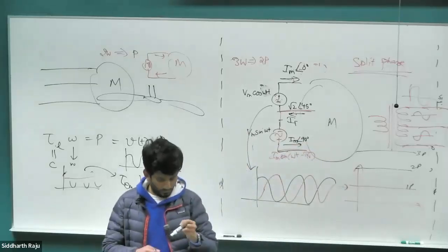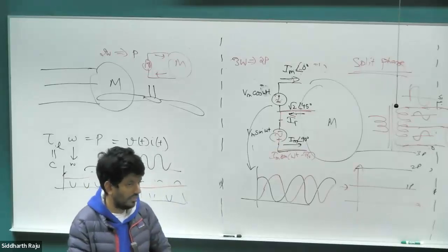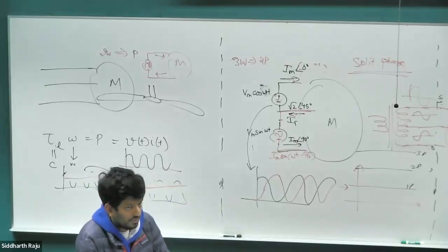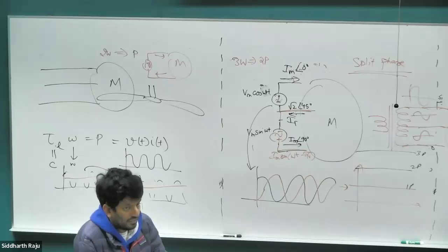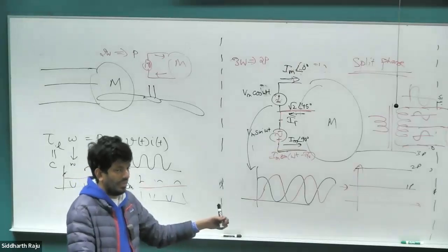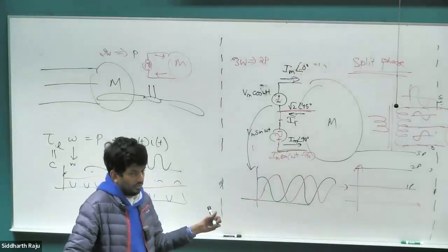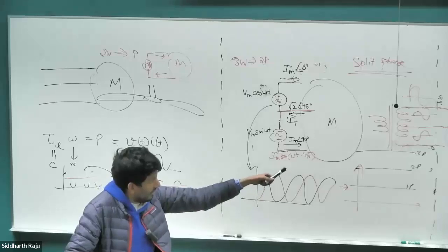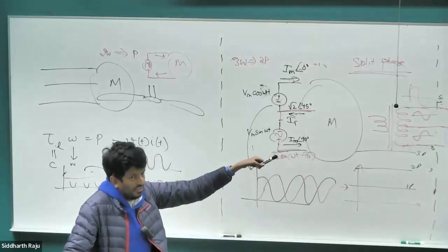Yep, Thomas. When you wrote the first two currents, both had 5 amps and then the last one had minus 10 amps. Yeah. That was at an instant in time. At an instant in time. Not an average, the magnitude of them. Okay. The magnitude would all be the same. The average, they would all be zero because these are sinusoids. Right? So the phasor magnitude, when I drew their IA by the IC, those would all be the same for all three of them.